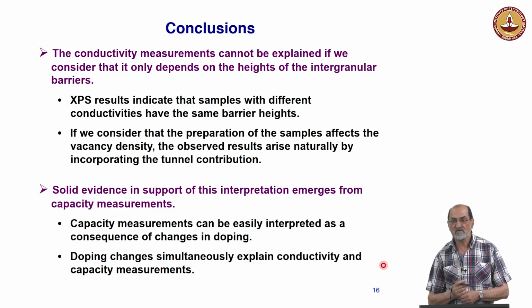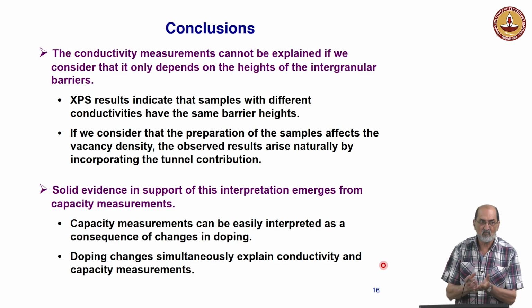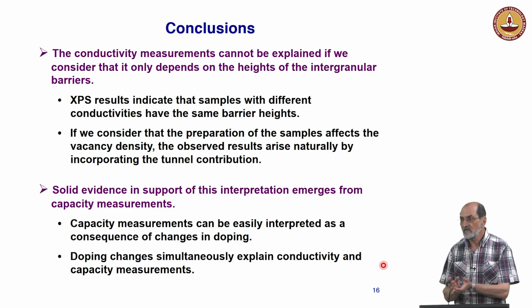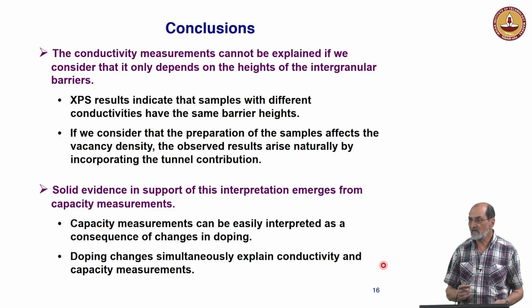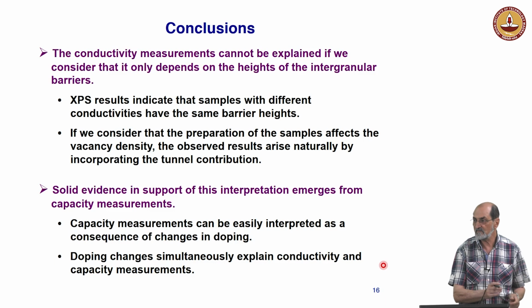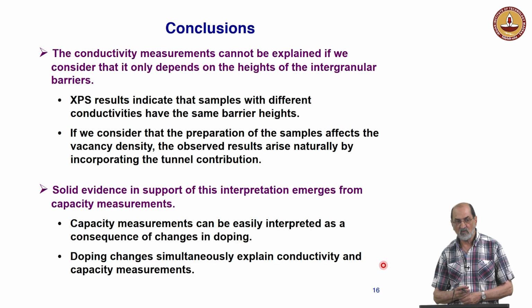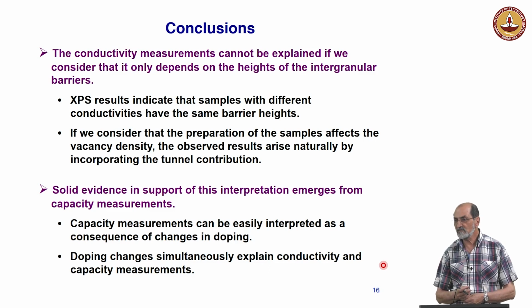Right? So this is much more complicated than typical studies in materials and electronics, where the dopant concentration is always the same. You decide what the concentration has to be. You ask a guy, okay, I need silicon with this type of doping, and I want it to be N-type, with 10 to the 17 per cubic centimeter of phosphorus. Okay, here's the device, the material. And you have the material with that doping concentration. Well, here that is not the case. You have no idea what the dopant concentration is, and also it can change.